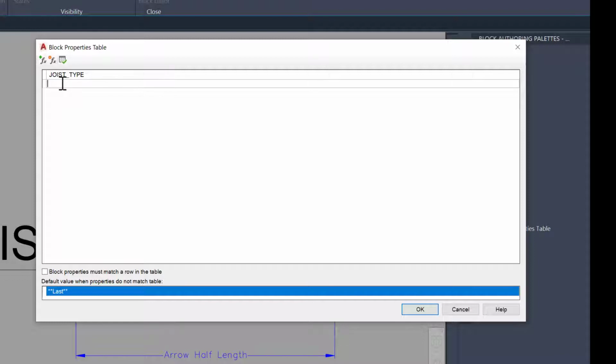So we're going to type in 11 7/8 of an inch, TJI S31 at 16 inch on center, complete width 3/4 inch OSB, glued and nailed.